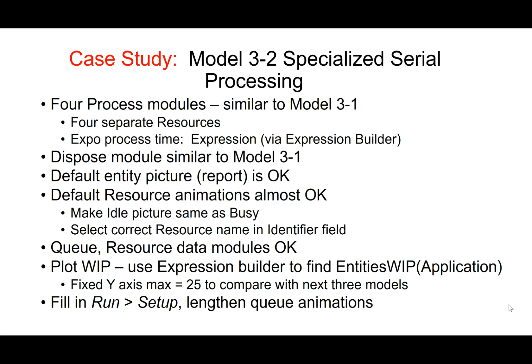Create the 4 process modules similar to model 3.1 using 4 separate resources. The expo process time will be an expression via the expression builders. The dispose module time you can create similar to model 3.1. Use the default entity picture.